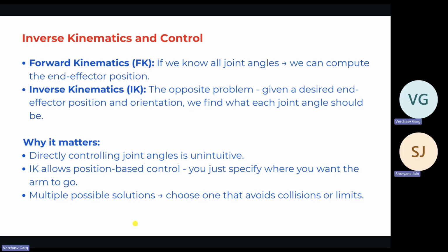What answers: x equals L1 cos theta 1 plus L2 cos(theta 1 plus theta 2). Right? For y, this is theta 1. I will do this. And for y it is L1 sin theta 1 plus L2 sin(theta 1 plus theta 2). Okay. So now what can I do?